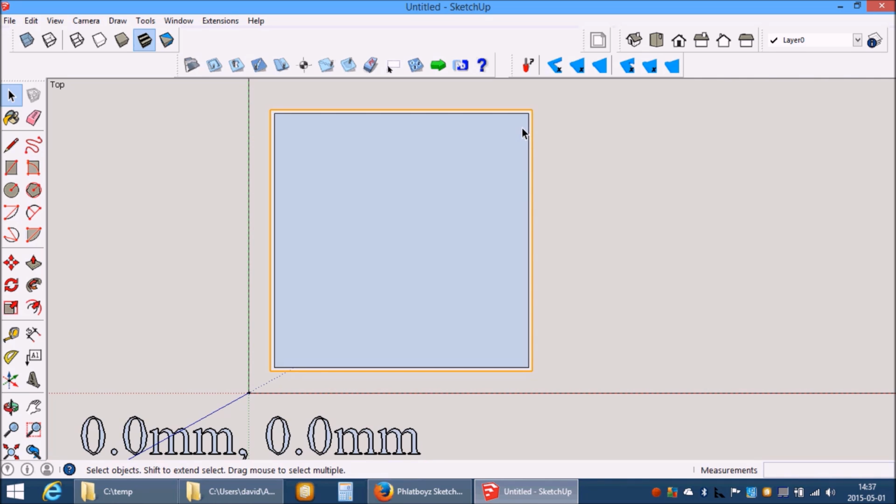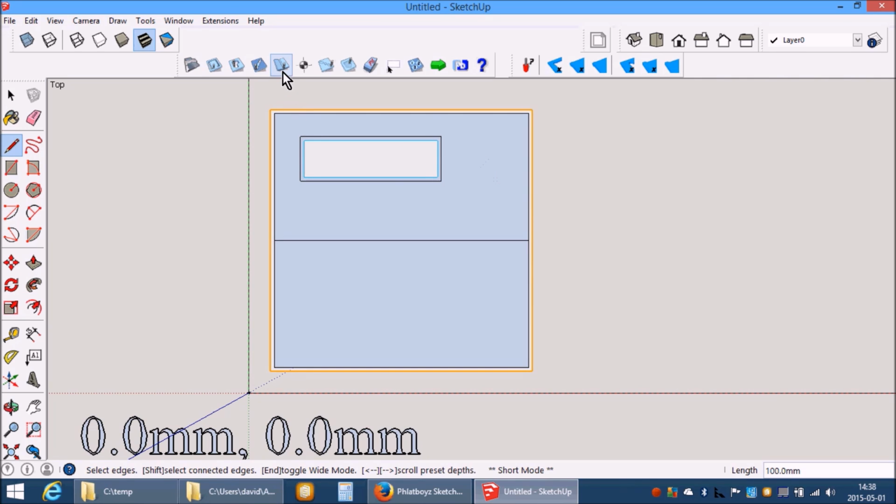So what else can we do? We can cut internal shapes with the inside cut tool, which automatically puts the cut line on the inside of the shape. If we have a line across our object where we would like to cut, say, halfway through the material so that we can fold it at that point, we can use the fold tool.